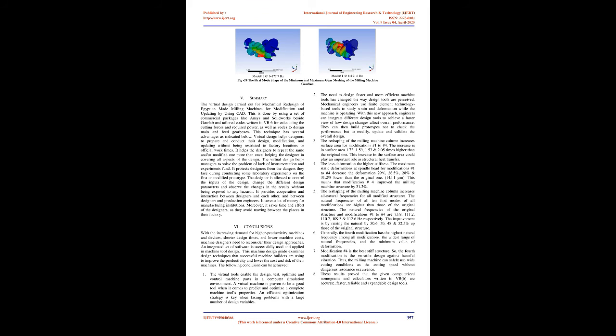The maximum deflection is 13.51 µm in the y direction at 475 Hz, and gear meshing frequencies. The frequencies of the gear meshing are defined in Hertz, or cycles per second. Gear meshing frequency is a harmonic phenomenon and it can be calculated by the following equation: F equals z times n over 60, where n is the rotational speed in RPM, at maximum speed and at minimum speed.